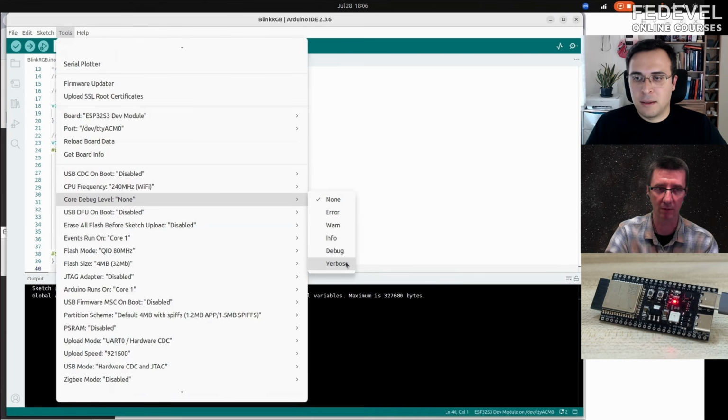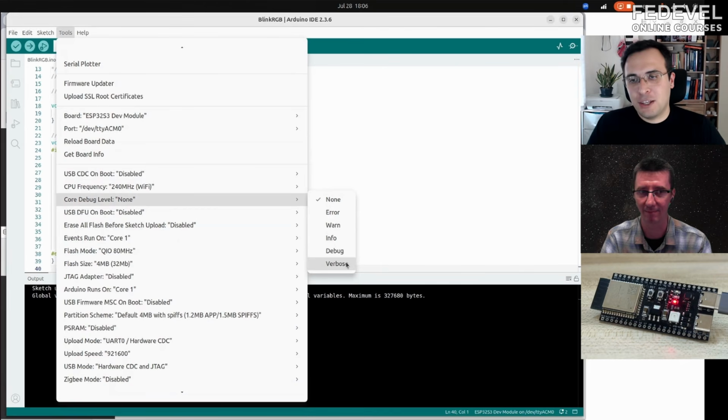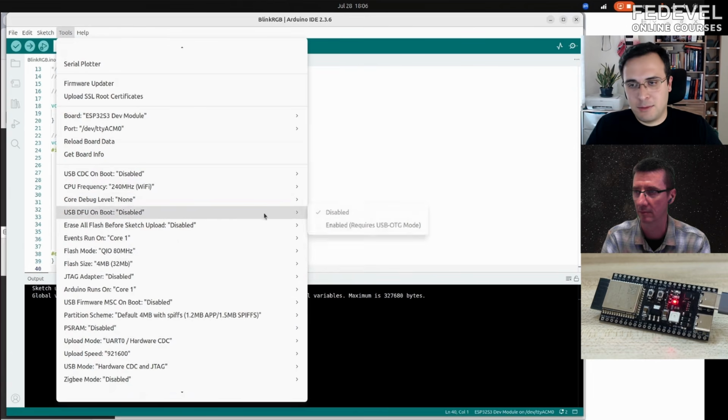There is also some kind of debugging option even in this Arduino environment, but it's not like debugging in the Espressif environment, going through line by line. It doesn't go through line by line, but it prints the debug outputs, lines that you have already put in your code or that come from the SDK. It is a pretty good feature. If you are going to use interrupts, I recommend not using any sort of print inside the interrupt, because some interrupts you want to take in microseconds, and when you use a debugger, it makes it slower.